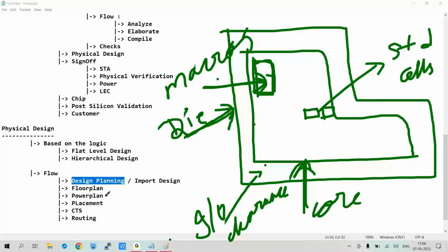As we have only a short time, we cannot take that much risk, so there will be a separate engineer for that as well. So you are going to be working in floor plan, placement, CTS, routing majorly. And also the sourcing of the power plan script and the fixes provided by the equivalent engineer will be done.